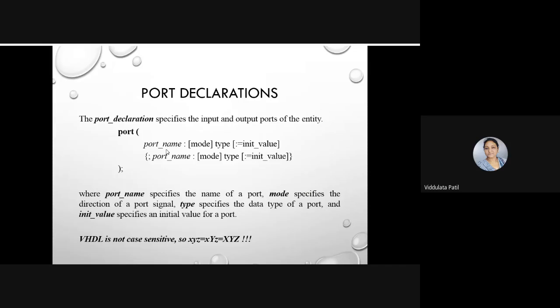For example, if you have declared the port name as XYZ, then whether you use X, capital Y, capital Z or all capitals, it will not make a difference. It will be considered as XYZ only. That is one of the features of the VHDL language, that it is not case sensitive.